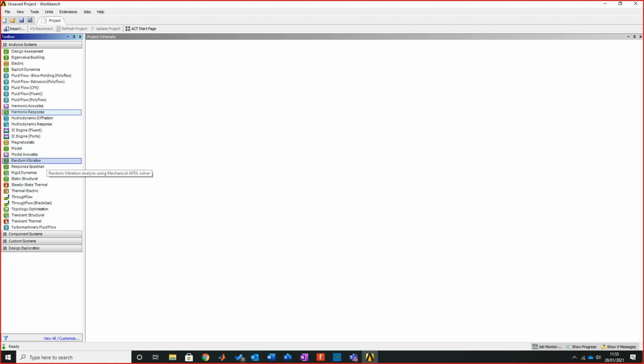But what we are going to be looking at today is a static structural. This is because we know what the maximum force should be on our truss example. Interestingly, a lot of people have said we never calculated a material for it. That's because the force applied will be applied to any material. If there is 18 kilonewtons there, it will be 18 kilonewtons applied to titanium or to steel. It would still be the same force regardless, because it's all down to geometric representation.